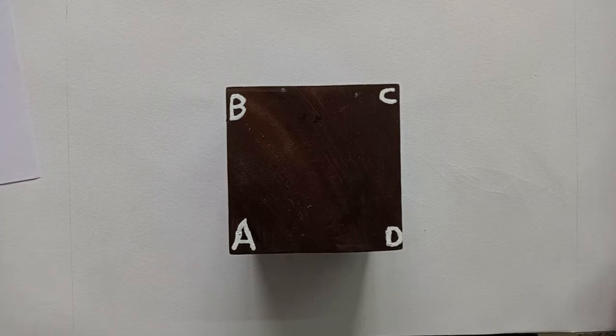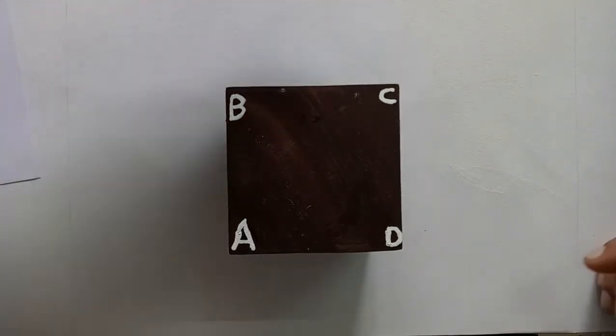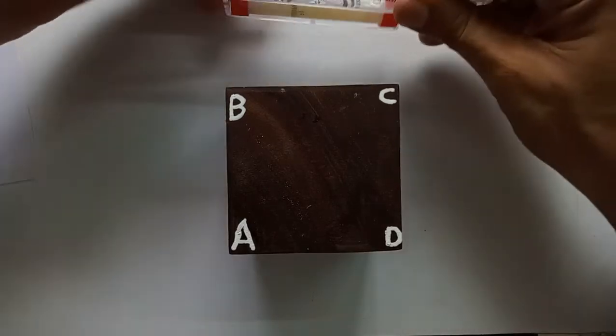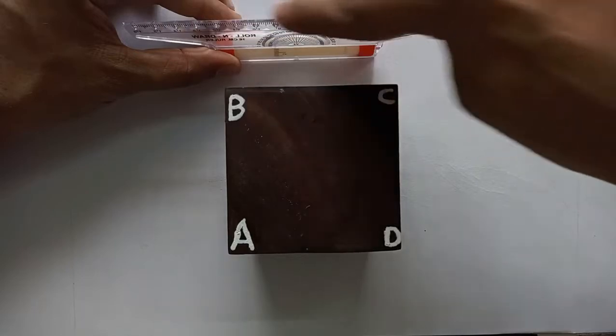When drawing the top view, the xy line will be our reference, and in this case the distance with respect to the vertical plane is not mentioned. So you can draw this top view anywhere below the xy line, but you have to remember that one of the square faces must be parallel to VP. Let us imagine that this is our vertical plane. When you are observing from the top, we can see it as a line.